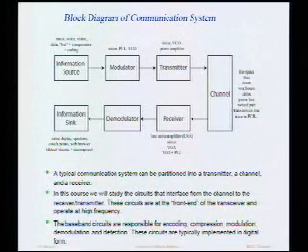And we generally put coding on the bits. The reason we put coding on the bits is we want to be able to detect errors in transmission, which can be very common for certain types of communication. As you can imagine, if you send information down a wire, it's probably going to be a lot better than sending information through the air, because through the air, the environment is constantly changing. There's multiple paths from source to receiver, so the probability of error is higher. So coding allows us to detect when errors occur and allows us to sometimes even correct for those errors.